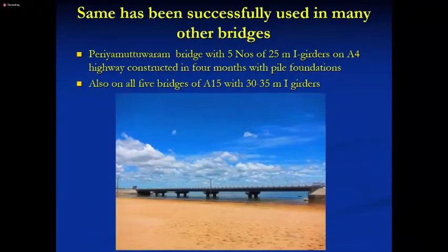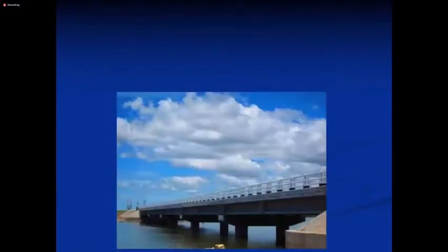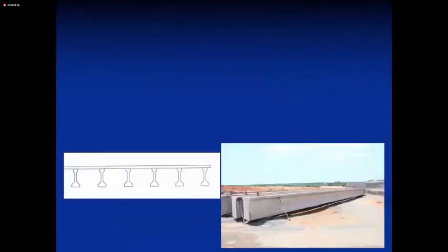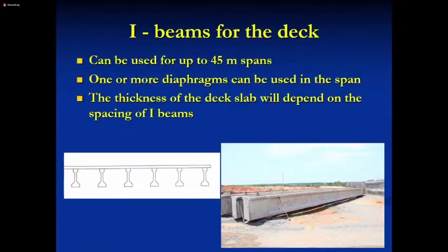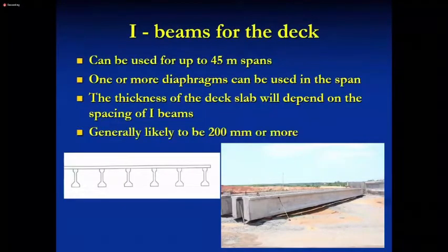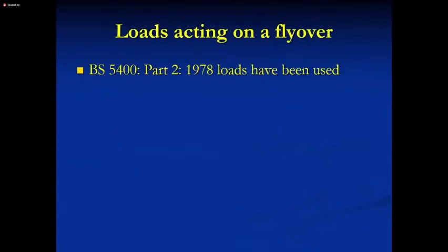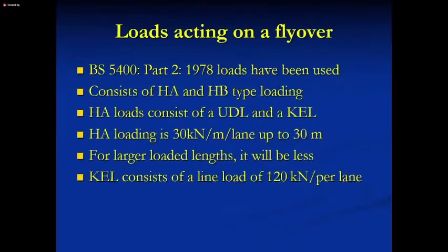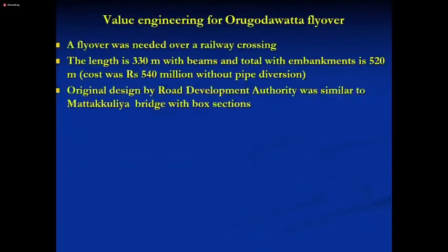Right. Okay. So this A15 highway bridge and the same bridge, and there's another second bridge also constructed, 3 span 75 meters, again by Marga. So these are the photos of that particular bridge, I girders. They can be used up to 45 meters. And so loads acting on a highway can be different.